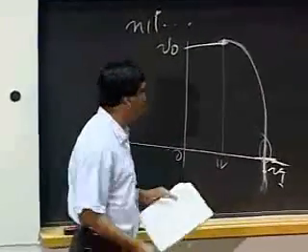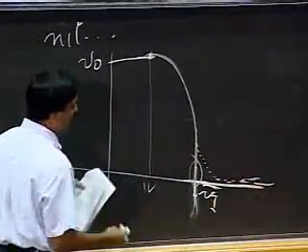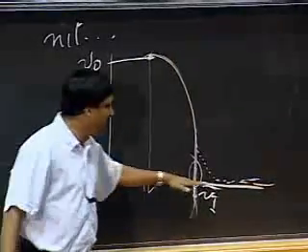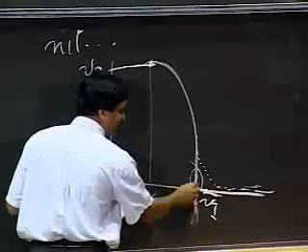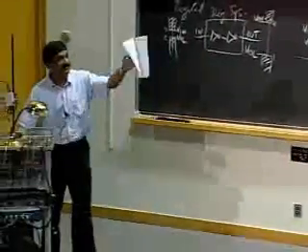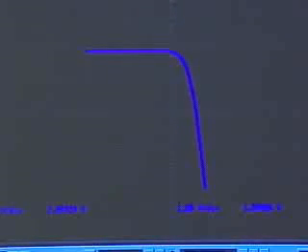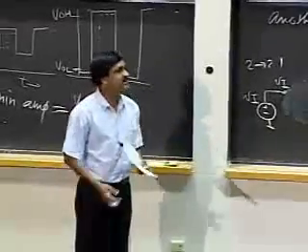It begins to behave more and more like a resistor, and what happens realistically is that the output goes down and then becomes a zero-hugging line. I'll show you that in a second. In this particular device, it doesn't really go down here. Let me just show you that part. For that device, mathematically, just by that model, it should have gone through the floor and punched through to the corridor below. But this is a practical device, and the model breaks down, and that's what begins to happen. The device stops behaving like a dependent current source. Rather, it behaves like some corny old resistor and saturates out.